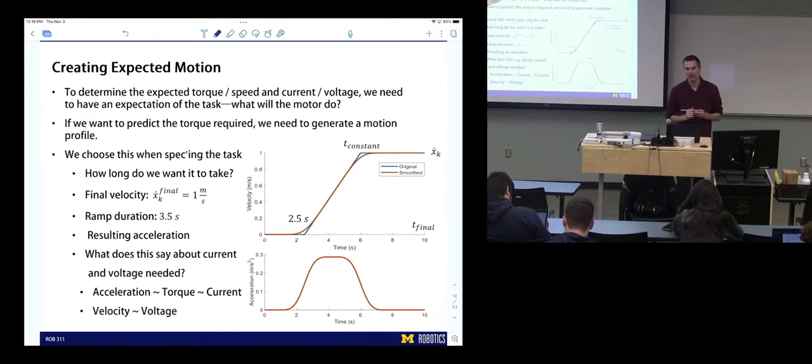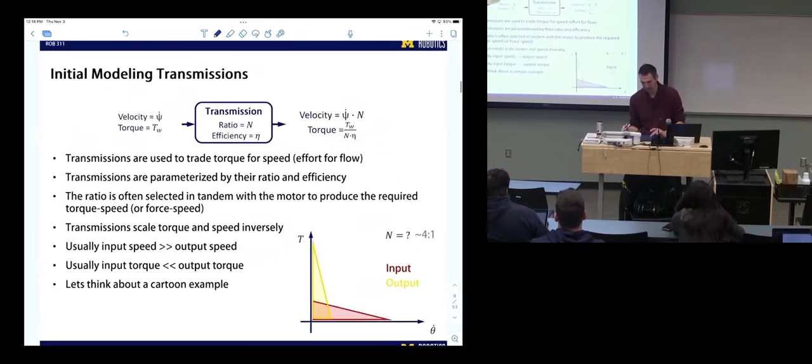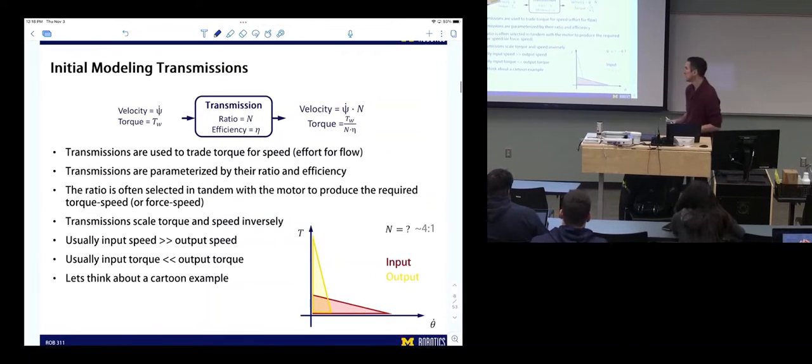I actually have a question about one of the other slides with the torque and speed. I'm not confused about it, but I want to understand better: why do we tend to want lower speed, higher torque on the output versus the input? Yeah, good question. The reason for that is most power, the capacity to do work, comes from machine elements, usually in the form of speed. So motors can run really fast.